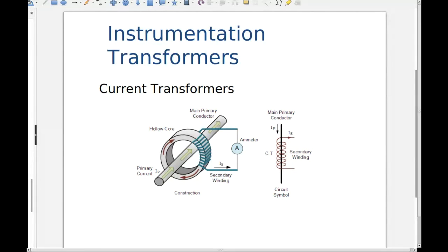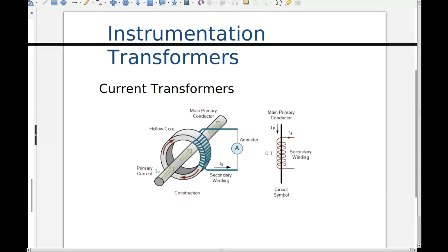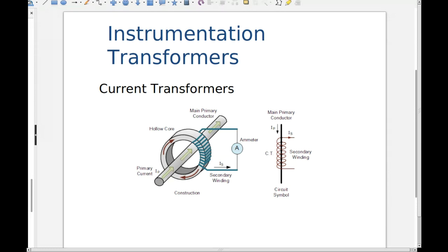So in this case, the primary side only has one winding basically. Okay, so there's like one winding. It's not even a complete winding. It's just that wire running through there, but it's such a huge current that it's generating that magnetic flux, and we're able to run that into our meter.